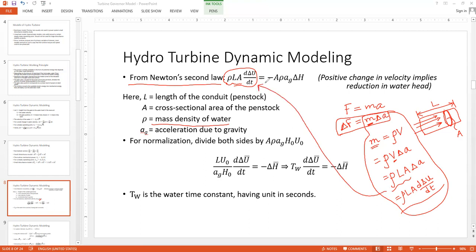That is done. So the part that is left is basically related to the force. And how do you relate force with whatever is appearing here? So let's see. Again, we have to take some help of some basic physics. So force and pressure, what's the relation? We know pressure is force per unit area. And again, this is the cross-sectional area. So force is pressure, water pressure, into the cross-sectional area through which the water is flowing.